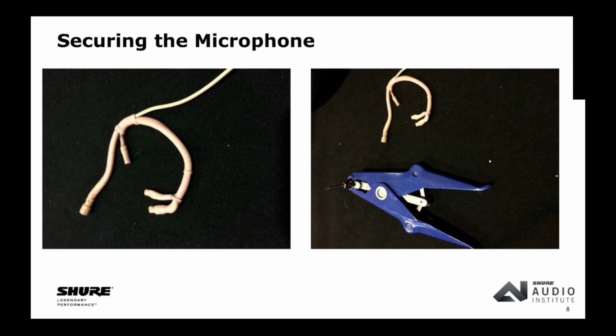And Hellerman sleeves, which are what these tan sleeves are, are a cable management product that are a very stretchy latex tube used for doing cable bundles and industrial wiring and stuff like that. But by the nature of being latex, as long as you don't have a latex allergy, it works very, very well. And the tool, you actually wet the tool, or you can get actual special lubricant if you want.